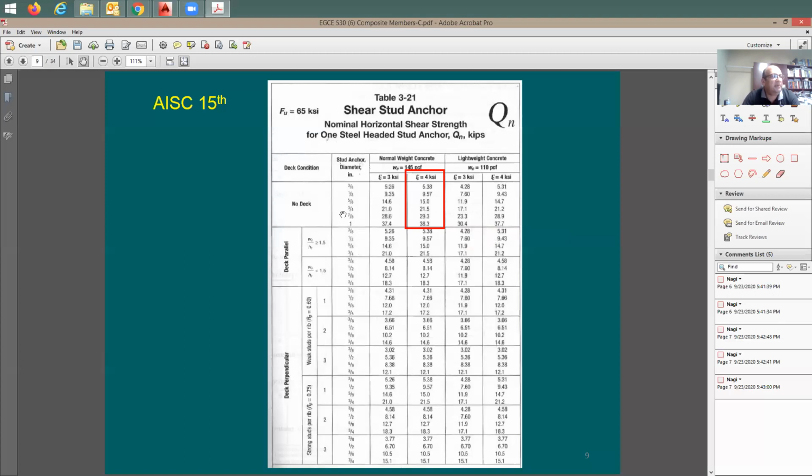So most likely I'm going to be going here with 3/4 inch. So if you're doing your homework or doing the project, you can go with 3/4 inch. And if you really feel that this number 7/8 inch, which is 29.3 kips, let's say if you have 4,000 psi for the concrete, or 3,000, if you feel that shifting it up or using 7/8 inch instead of 3/4 inch to make the spacing of the Nelson studs about 12 inches, go ahead and do it.